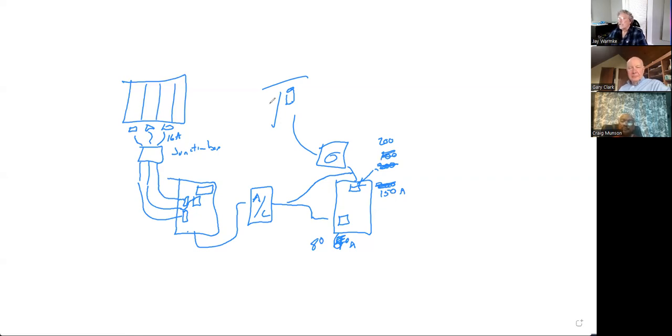The only danger there is, you don't have to get an electrician, but bear in mind when you start disconnecting your main, I'd like the power to be turned off before I do. Yeah, no kidding. So that meter box has to be removed. So you're probably still going to have to call AEP to have a service interruption, because they don't want you messing with the meter.